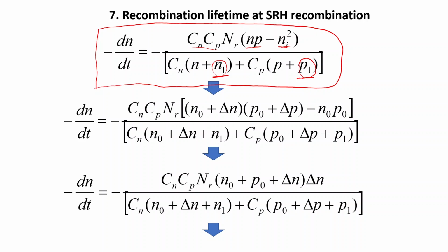in the semiconductor. After several modifications, when we consider that N is actually the sum of equilibrium and non-equilibrium charge carriers, delta N and delta P, and assume that delta N is equal to delta P, then we can also express ni squared as a product of equilibrium charge carrier concentrations in the conduction band and valence band.